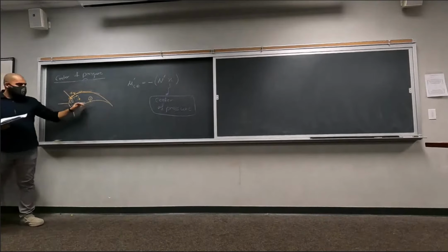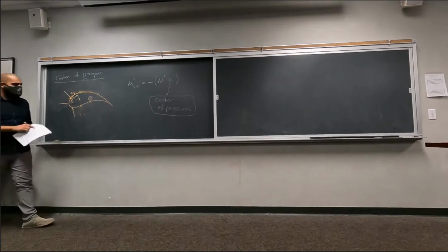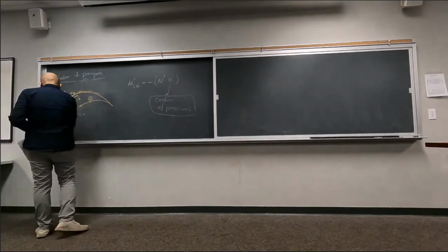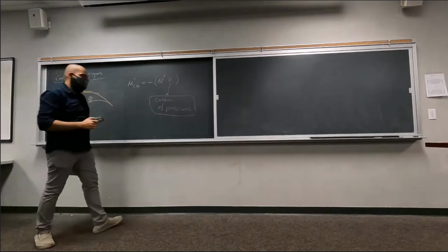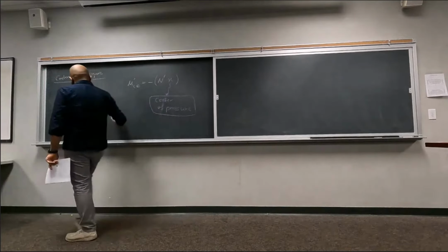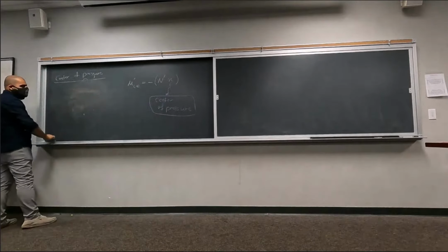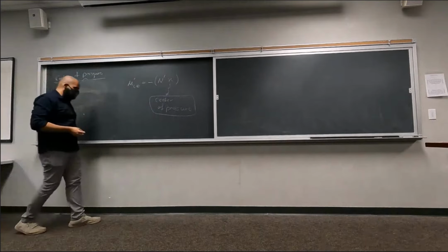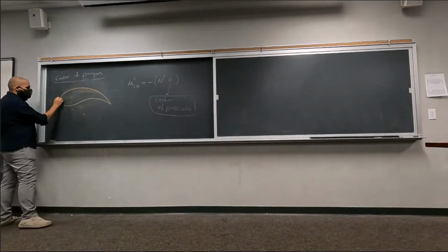So all of these pressures and shears apply a moment on each location of the body. We are looking at the point at which all of the moments will cancel each other out. Okay? So since we already can calculate the moment at the leading edge based on the equations we have, and we usually put the center of the coordinate system at the leading edge, the distances are usually calculated from the leading edge of an airfoil.